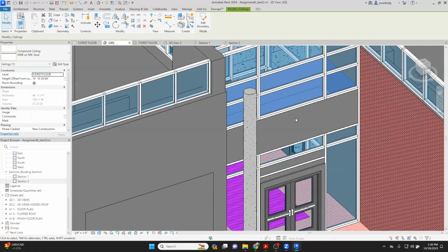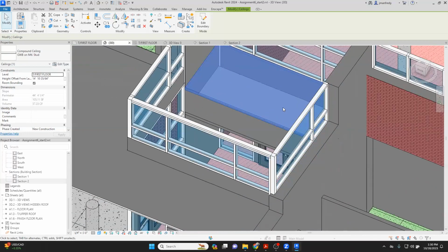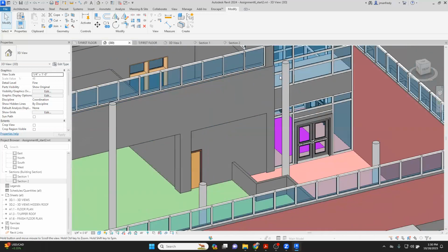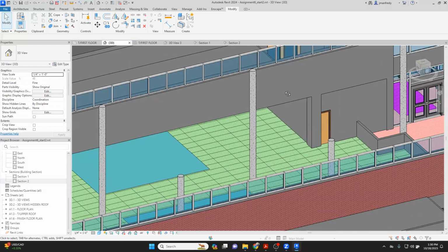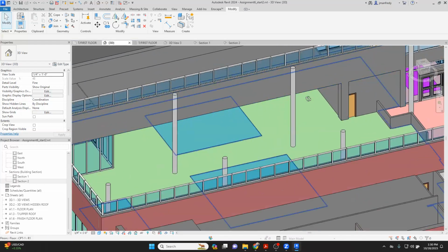This is like a teal color. And that box is the bulkhead. It's probably hiding mechanical ducts. But that's what we're drawing, using walls. Tools you already know. You know how to make walls, and now you know how to make ceilings. And a soffit wall is new.